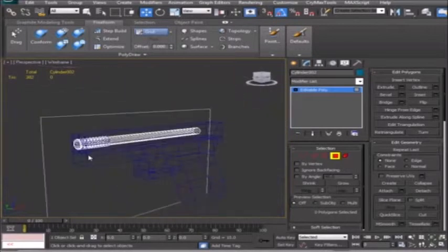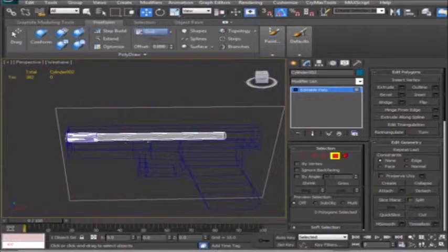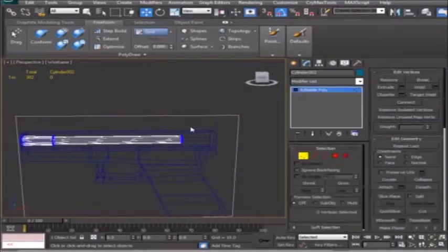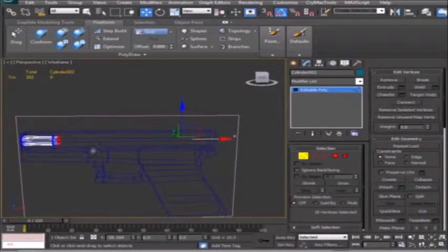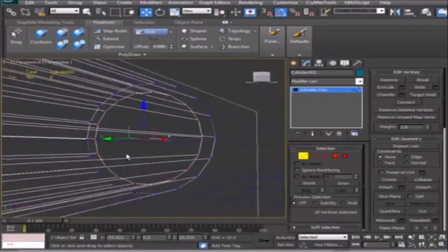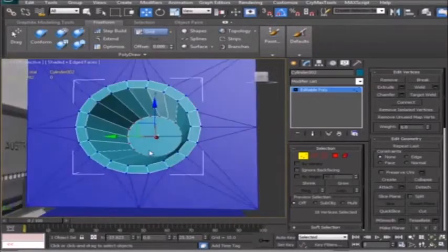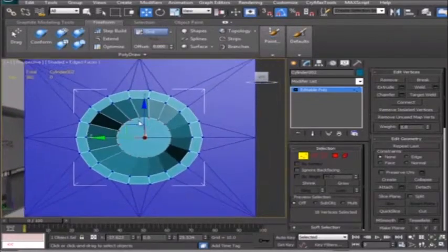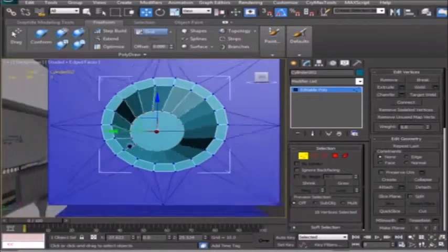I end up with a lot of texture space in here that's really just black solid color, so it doesn't do me any good to go that far back. All I have to do in reality is go to about right here, and then when I map this with the textures, paint this black and also make sure that the specular value there is black, and it will look like a void.